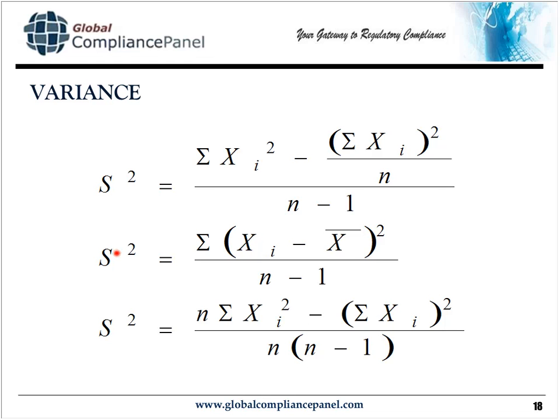And what happens is that you cannot simply add together 2 standard deviations, because 2 standard deviations added to each other, you have the result of the plus-plus addition, the plus-minus addition, the minus-plus addition, and the minus-minus addition. So theoretically, you have 4 different answers here, which drives everybody crazy. So if you work with the variance, it's a lot better.